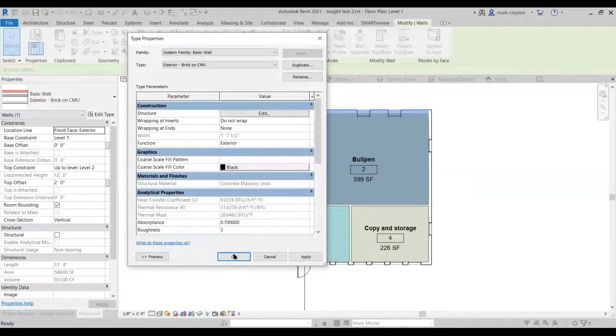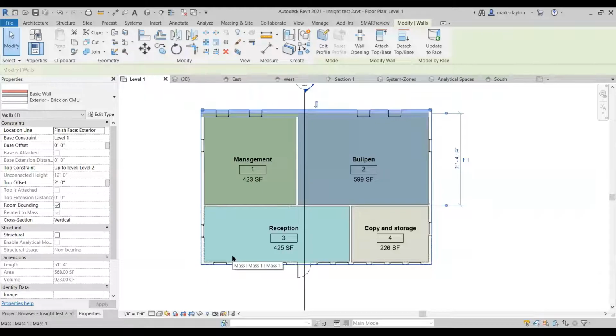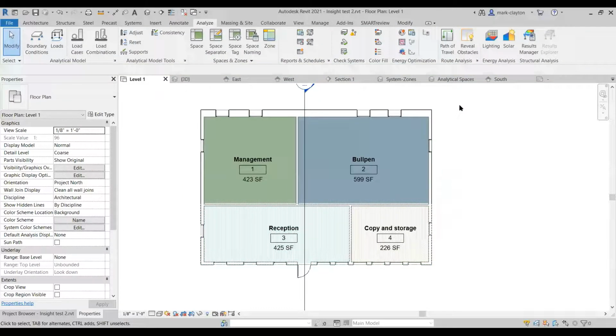Now, it's a great question, and here's some advice about how to think about this that most people don't do, but it really works well: think about what the wall types are in your building. You're going to have an exterior wall assembly. You're going to have an interior wall assembly. You're probably going to have a plumbing wall, because they typically are thicker than a non-plumbing wall since you've got to put pipes in there. Maybe you've got exterior plumbing walls and they're thicker than the normal exterior wall.